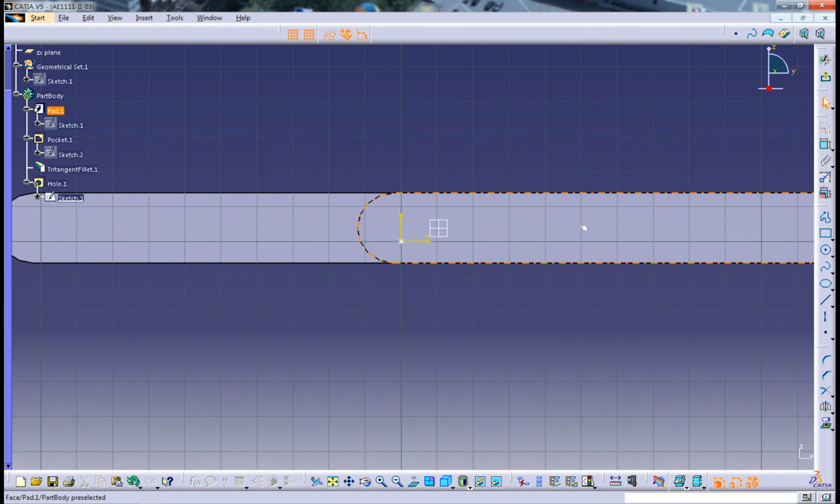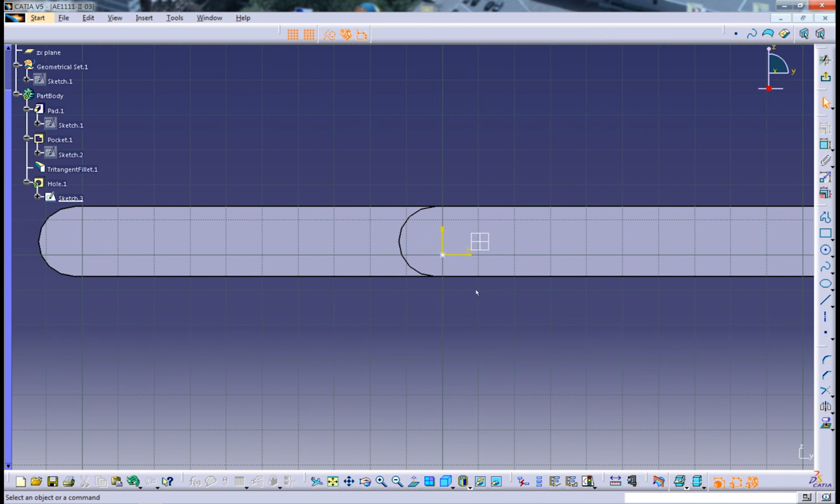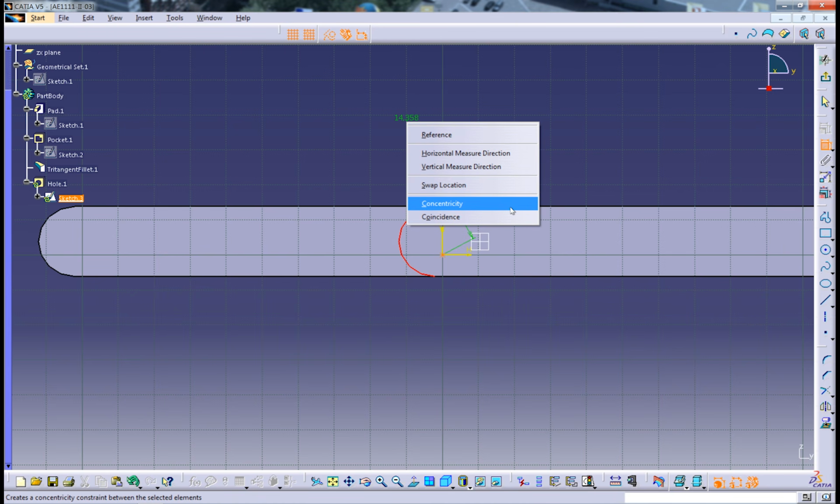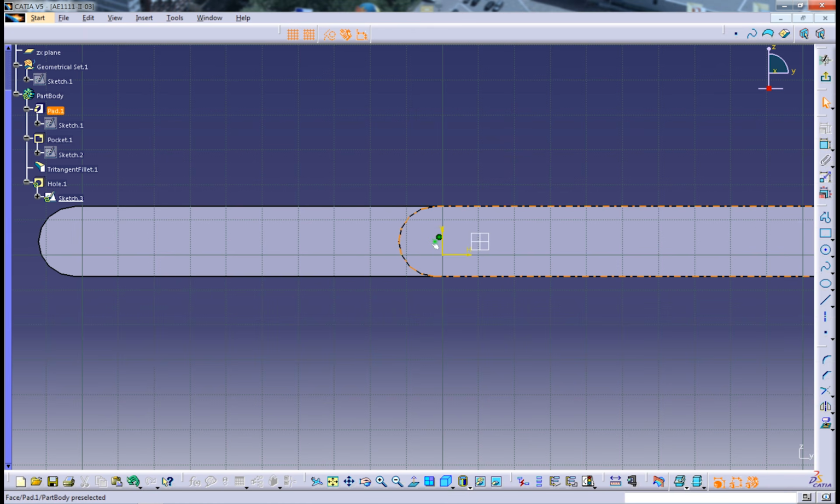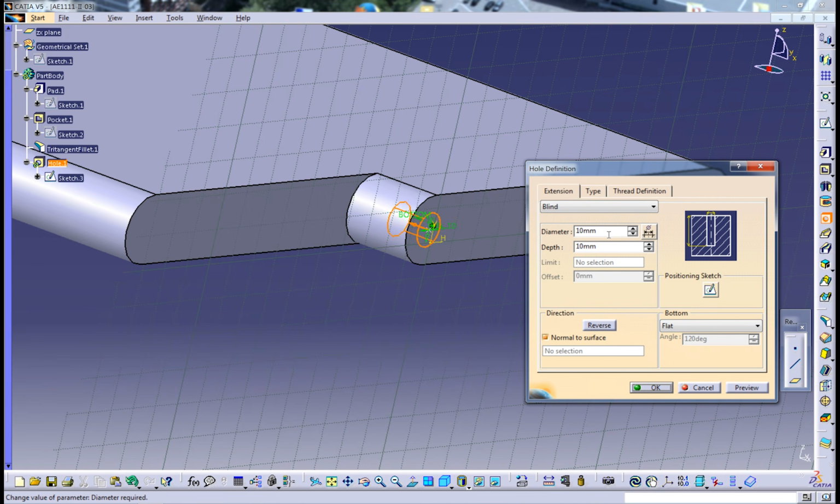Click on it, and then we change it to sketch mode. And this little white star here, this is our hole. Now we can constrain it like in all the sketches. We can use this constraint tool and click on our hole, this little star, and the arc where it should be concentric. Yeah, concentricity. So select concentricity, and it's directly in the middle.